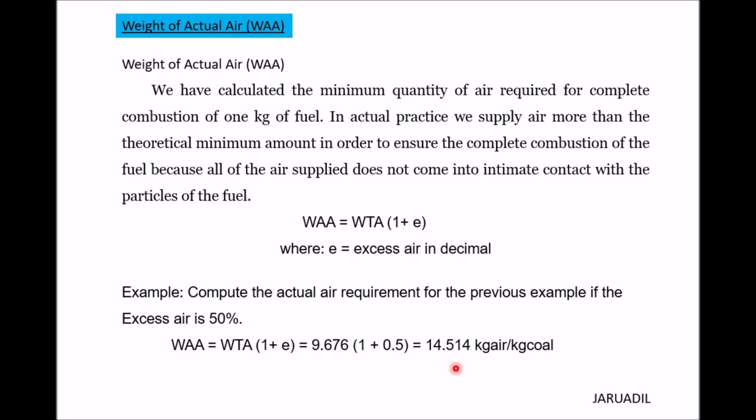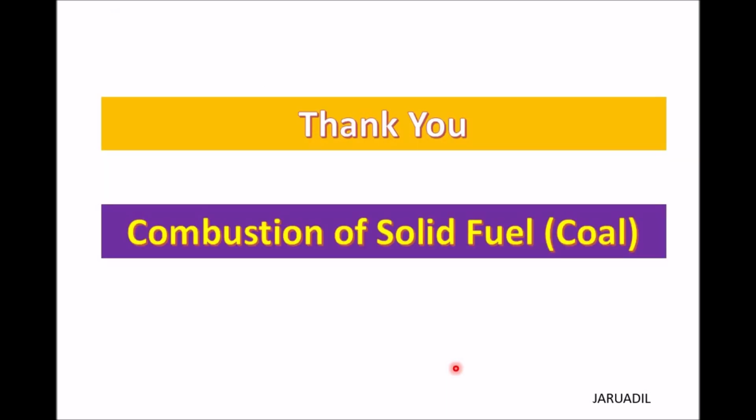So kung 14,514 kilogram yan per hour, so ano ang volume? So makokompute ka na uli. Kasi alam mo naman ang density ng air, di ba? So magdidire-diretso ng computation mo. Pag na-compute mo na yung volume requirements, so makukuha mo na kung ano ang capacity ng forced draft fan na kailangan mo sa pag-supply ng air dun sa combustion chamber ng coal. So ganun po ang importance ng knowing the weight of theoretical air and weight of actual air in combustion of fuel. So hanggang dito muna.